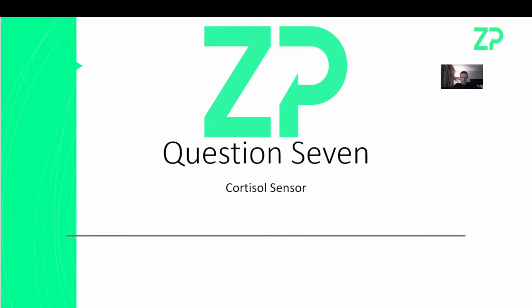So why do we need any bias relative to reference for generation 2 sensors? Because you are actually applying 0 volts. If you didn't apply anything, you just turned it off, there really is no energy being applied. So you kind of think that 0 volts versus reference is 0 volts. But when you think about your electronics, there is a ground in there. So you're not necessarily applying 0 volts versus ground. You're actually applying 0 volts versus reference.